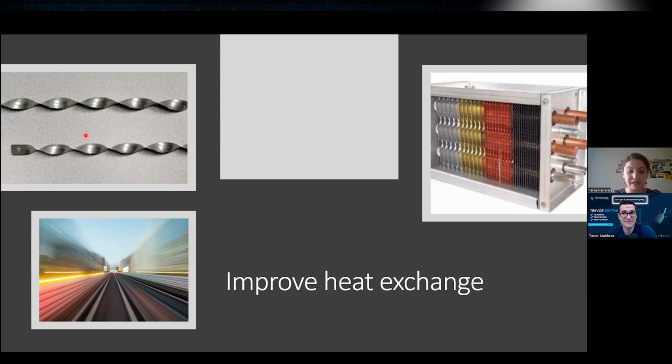Also, we can increase the passes. By increasing the passes in your heat exchanger, you will increase the refrigerant velocity. But of course, if you increase too many passes, then you will have a high refrigerant pressure drop, and your compressor will pay for that. Yes, we'll pay heavily for that. And actually, when you have a really high pressure drop, the performance doesn't improve. So there is a range where we can increase the passes and we will have a better performance.